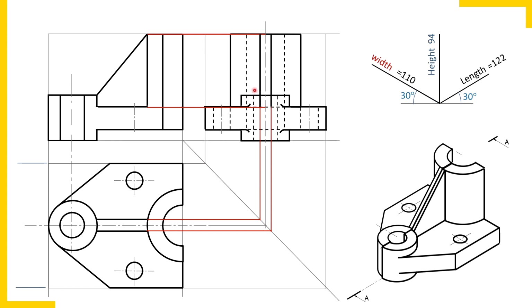Immediately you will realize that I am making a mistake here. Do you know what it is? Two visible edges don't intersect. So, correction. Try to understand, the logic is the same which we discussed earlier. Here is the cylinder, and this strip is the trapezoidal plate. The side view of the cylinder and the side view of this trapezoidal plate overlap.